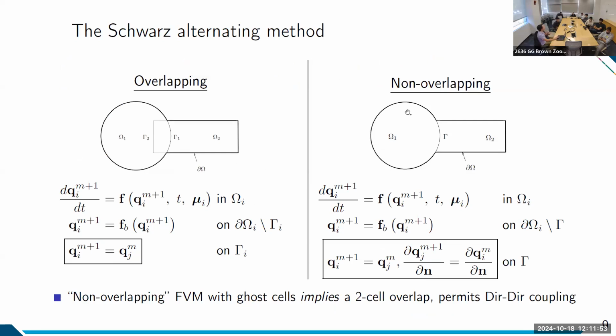But if you are using a non-overlapping decomposition, which is typically more natural, say if you were to have a contact problem where two subsystems were just bordering each other by a contact interface, that would be a non-overlapping Schwarz interface, and generally you will enforce an alternating Dirichlet and Neumann boundary condition. So one subdomain will transmit a Dirichlet boundary condition, and another will transmit a Neumann boundary condition to ensure convergence of your solution to the equivalent monolithic solution.